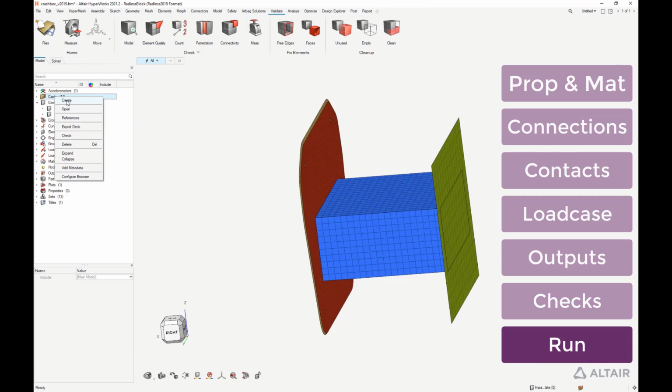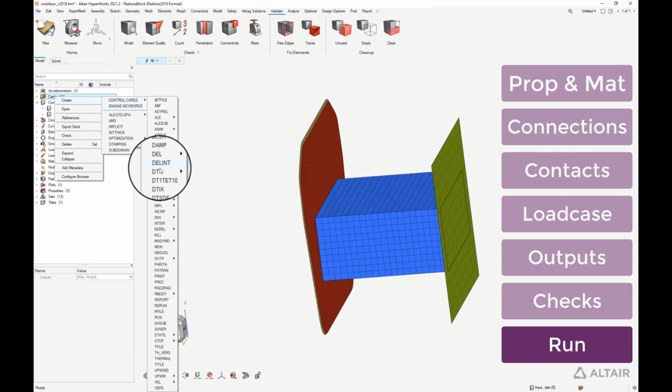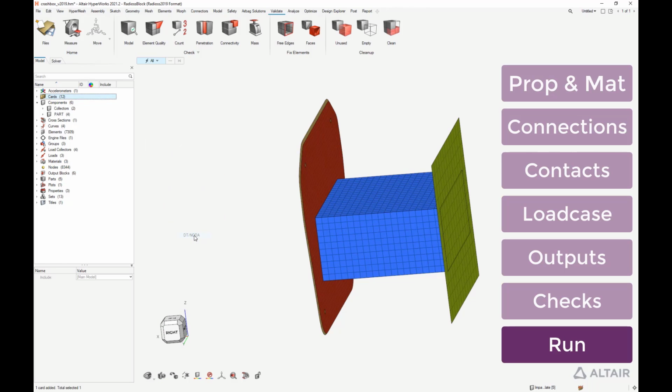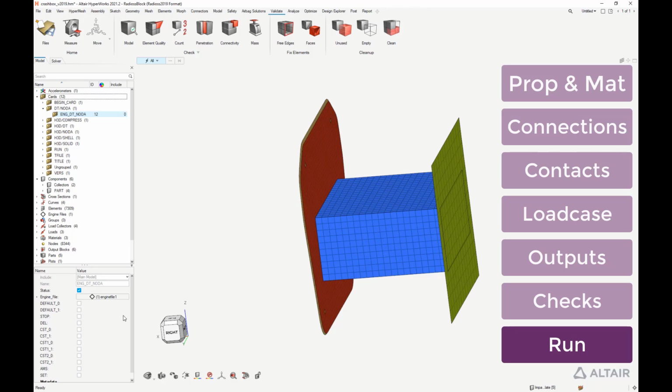There is the very last thing I'm going to add before exporting the input deck, a control for the time step. I'm going to define a constant nodal time step to avoid the time step from dropping below a given limit and the simulation stop progressing. As a counterpart, mass may be added to nodes if needed.